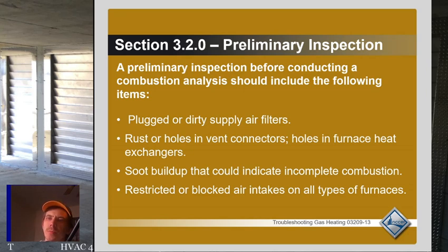If they stack too much stuff right in front of the combustion chamber, it can actually restrict the airflow going into the combustion chamber. If you have a 90% above furnace or something like that, then obviously the air intake going into the furnace can be blocked. So all of those things are important to look for. You should be checking that anytime you're working on a piece of gas equipment.